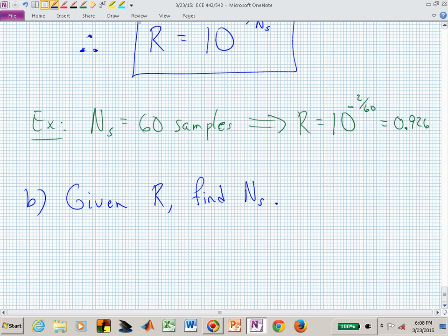Let's say you have 10 poles in your system and you want to find the dominant poles of those 10. Now I'm assuming they're all inside the unit circle, otherwise we wouldn't be able to talk about settling time, would we? We would have an unbounded response if we had one pole outside the unit circle. I now have all of my poles inside the unit circle.